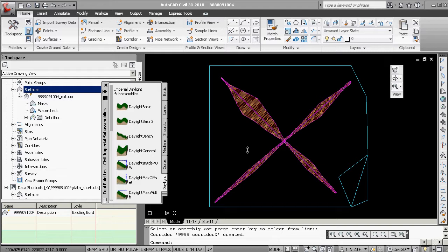From there we went and we created a proposed surface profile. In this case we did it by just drawing lines and using the Create Surface Profile tools. I still recommend that you do it on an ASCII file until you can really think in station and elevation. An ASCII file, of course, would be station, space, elevation for any number of PVIs, points of vertical intersection, and then you would fill in later with your curves.